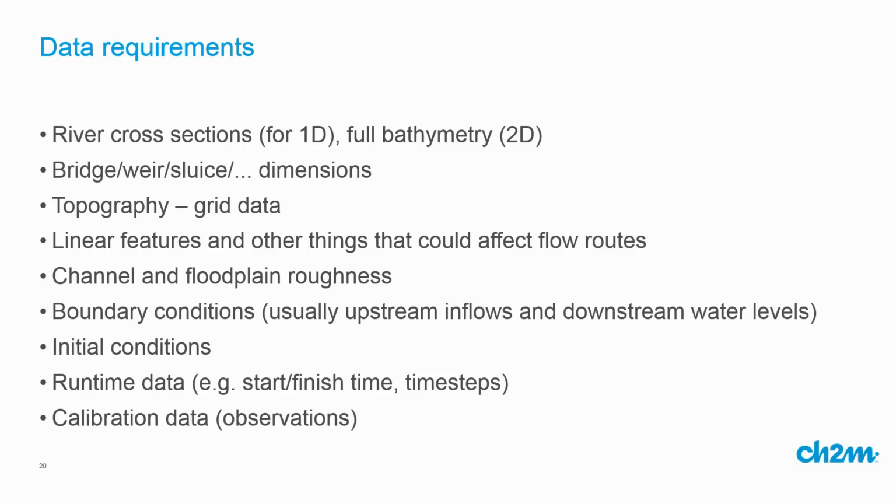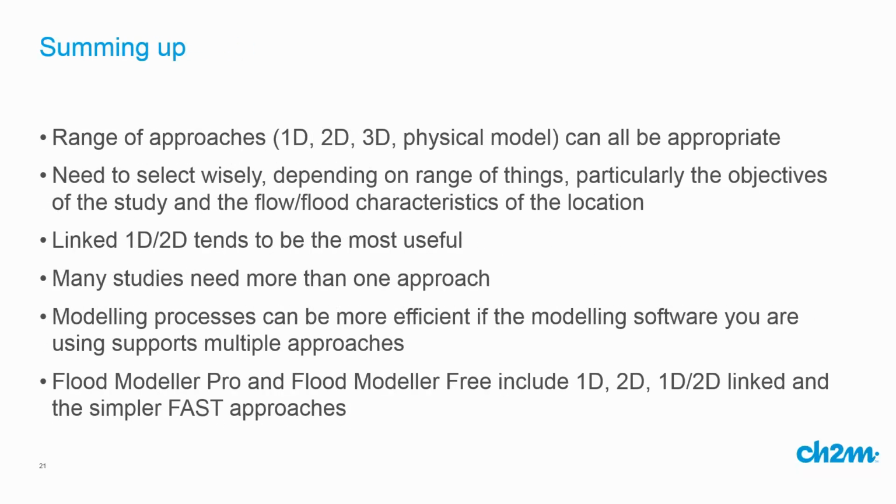Then if we're going through the calibration and validation process, we need to have some observational data, which could be observed flood extents, wrack marks, or it could be at gauging stations, what the water level or the flows were at those points. So we need this calibration data to help us get some faith in our models and model outputs. And that's what I wanted to say really to introduce flood modelling.